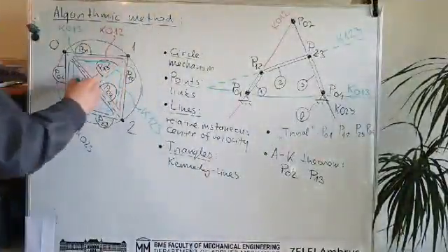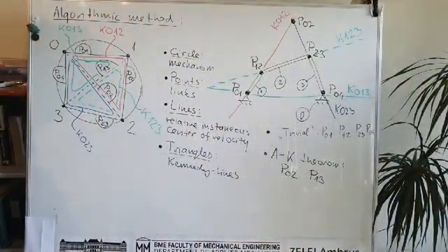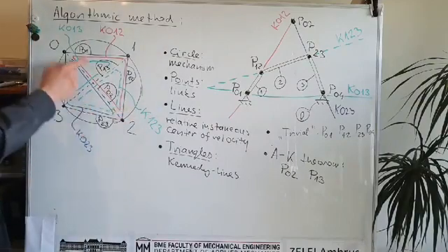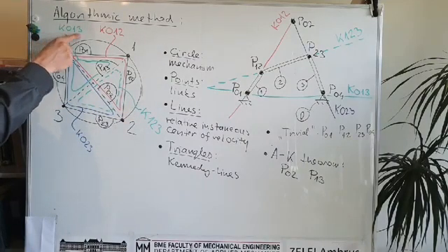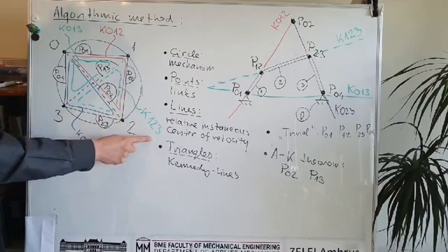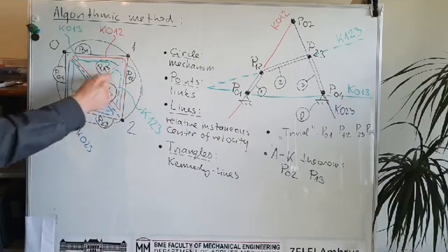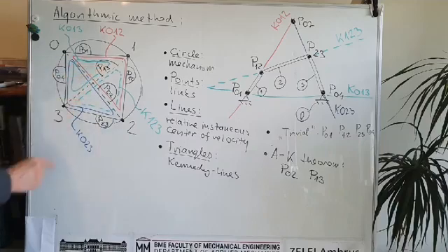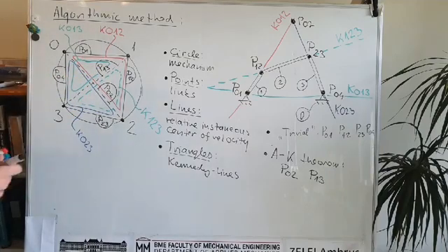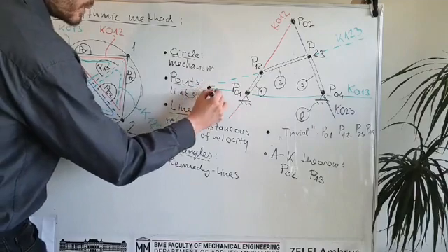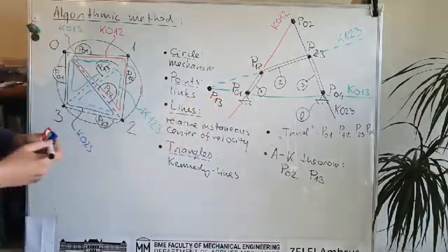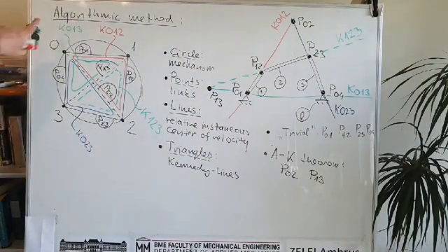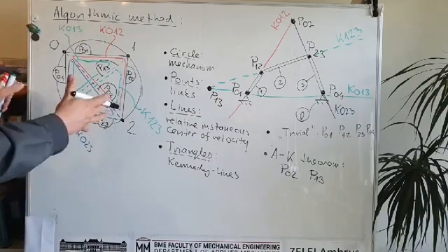It's already in the figure, and as we can see, the intersection point of Kennedy lines 0, 1, 3 and 1, 2, 3 gives us the location of point P13. So this is where we can draw P13. So this is how to apply this graph.